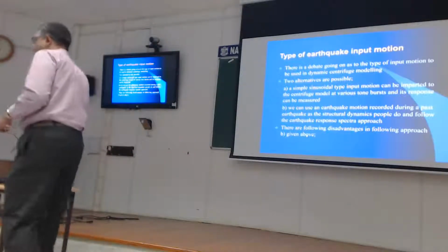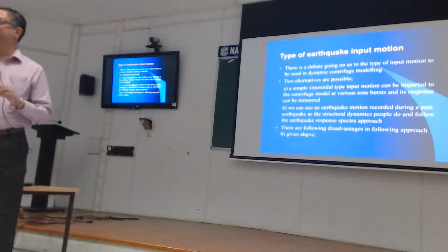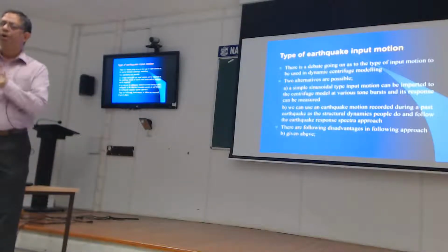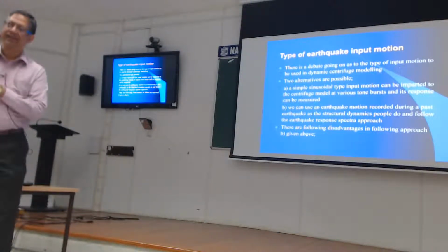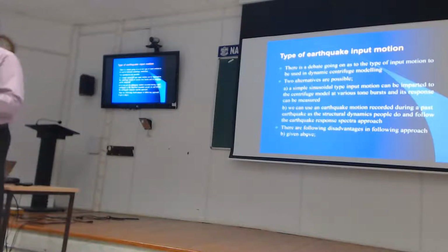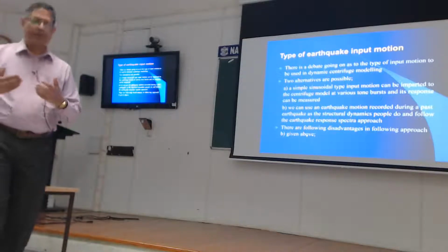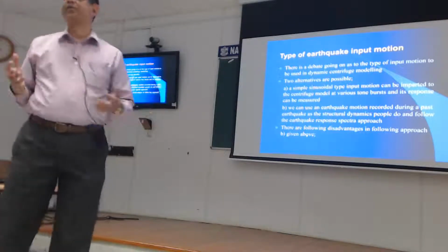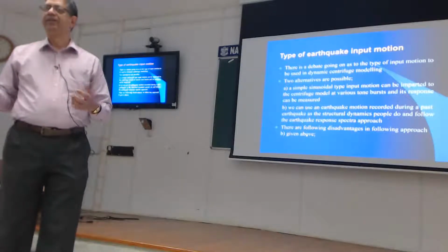The bigger advantage of doing pure sine waves or tone bursts is that you know the frequency at which you are putting the energy into the system. So if the system then responds with whatever it wants to do, you can easily detect the changes. For example, say you have a structure and the structure has some eigenfrequencies.